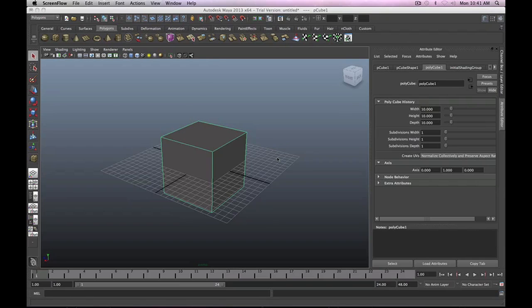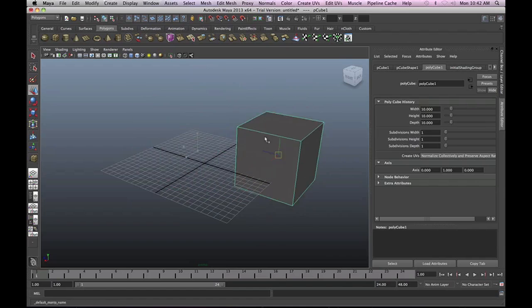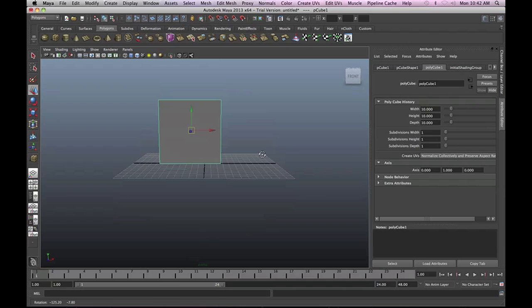The 3 key components to editing with polys are Translate, Rotate, and Scale. Over here on the left-hand side you have your toolbar. You'll notice that you're currently using the Select tool. While you have your object selected, click on the Translate tool. This will show the translate controls. You can click on each of the arrows to translate your object in that direction. You can also click on this middle square to move the object in every direction at once. However, be careful with this. Since you're working in 3D space, it's hard to tell where your object is going to end up until you change camera directions.